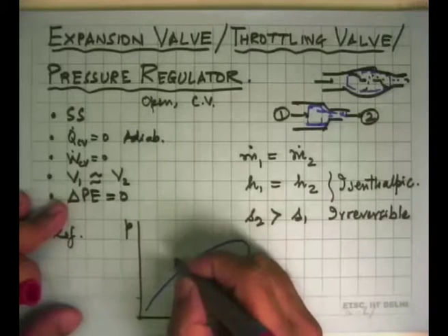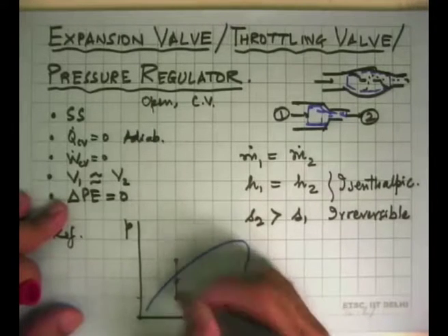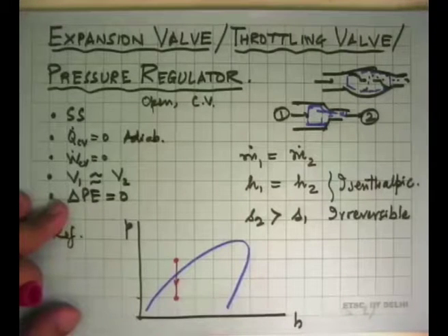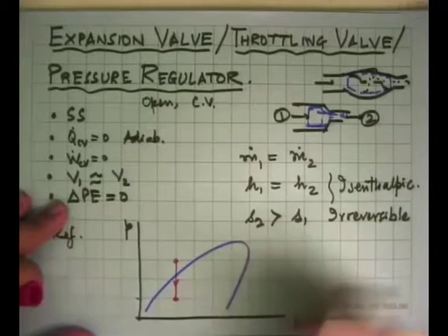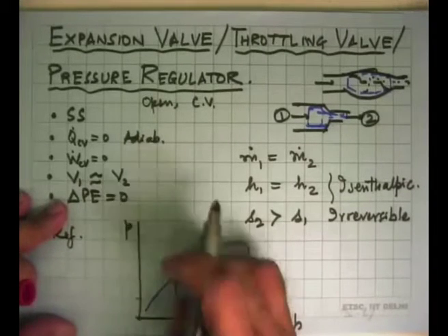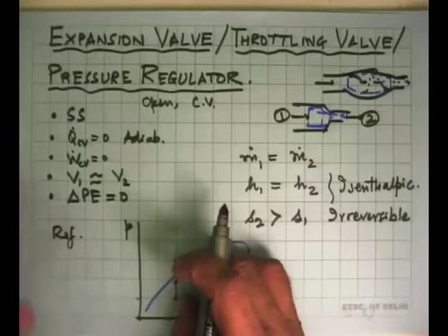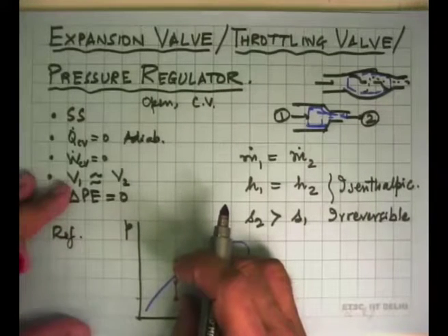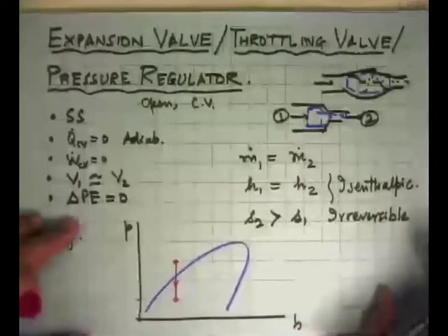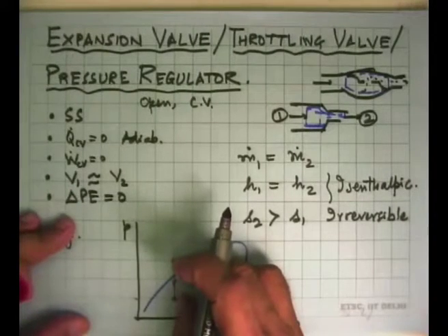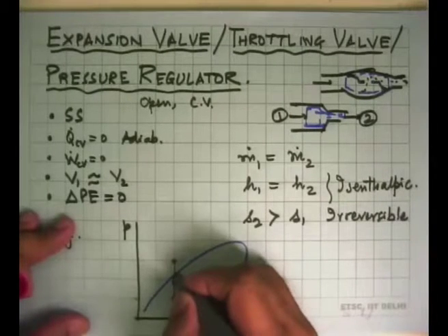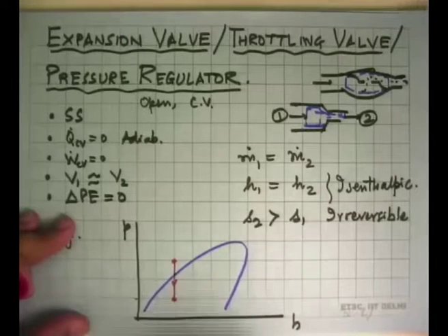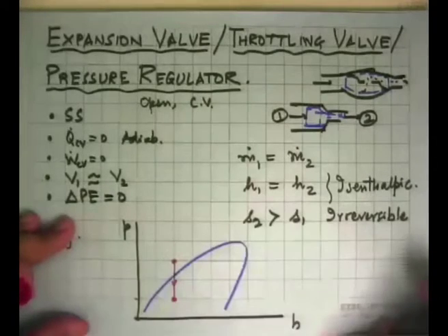One option is that, okay, let's put a small turbine, generate some work and come to this state. Entirely possible. Thermodynamically, it is entirely feasible. Practically, for the size of the machines that we have, refrigerators and air conditioners and even large devices like central air conditioning plants, the work output of this will be so small, the machine is complicated, and second, somewhere it is handling a liquid, somewhere it's handling liquid plus vapor. That makes the machine practically impossible to make in the engineering world.